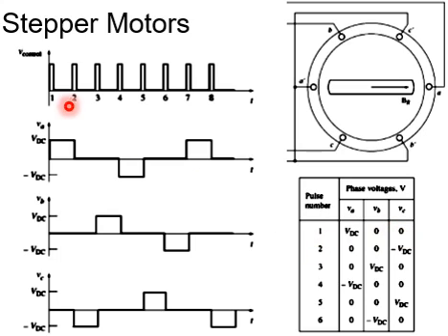At pulse 2, this is pulse 2 starting, at this point VA becomes 0, VB is 0, and VC is minus VDC. You can see minus VDC. So in this scenario it can be seen that the rotor is rotating in steps.